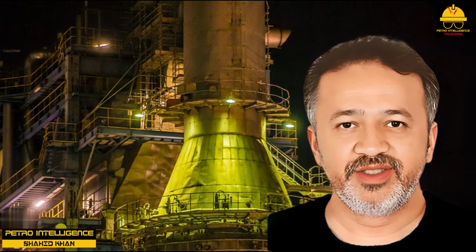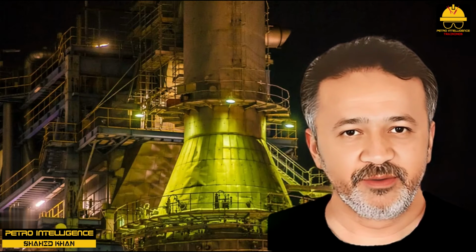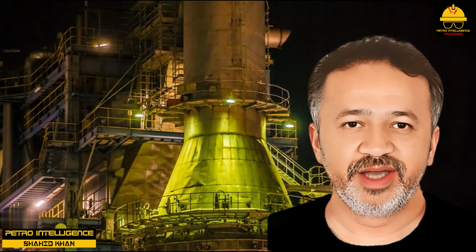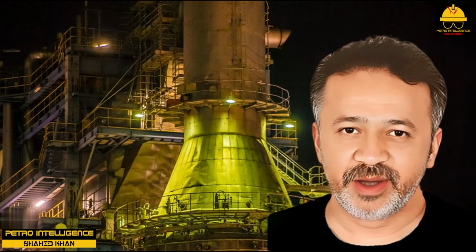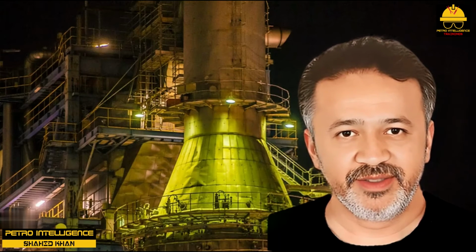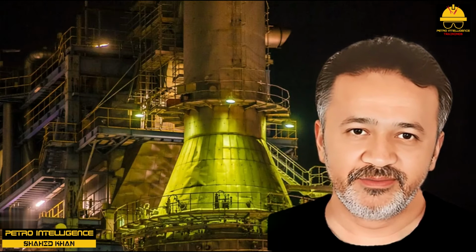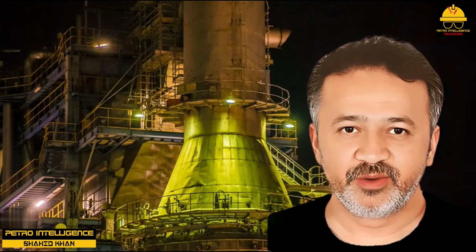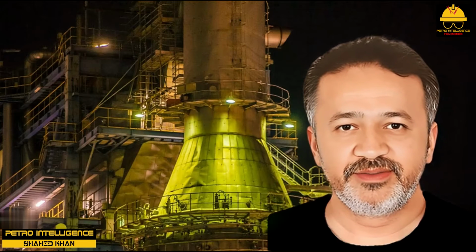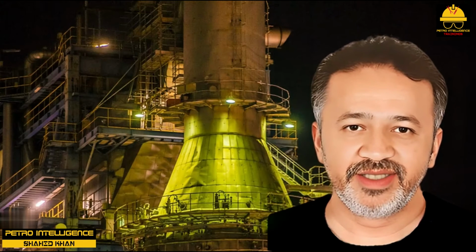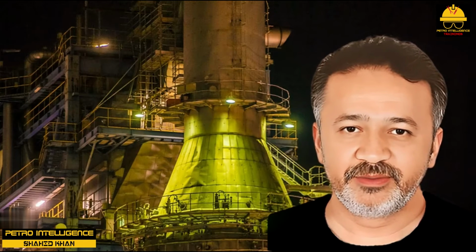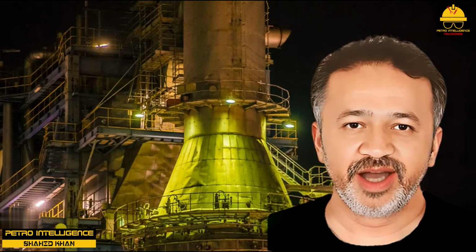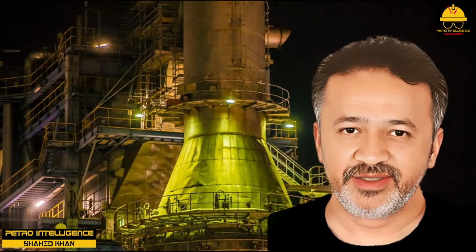The metallurgy of finned carbon steel convective section tubes is not designed to withstand high temperatures. The fins will become oxidized and, when cool, may become brittle and thicker than before, thus restricting flue gas flow. The convective section tubes themselves will become warped and bent and thus restrict flue gas flow still further. Just such a thing happened as a result of another well-intentioned but misguided attempt to improve fuel firing efficiency by reducing the oxygen content of flue gas in a fired heater.